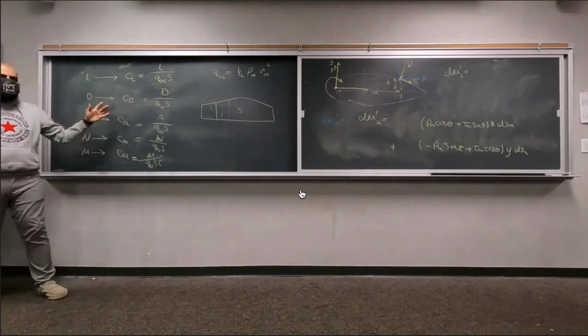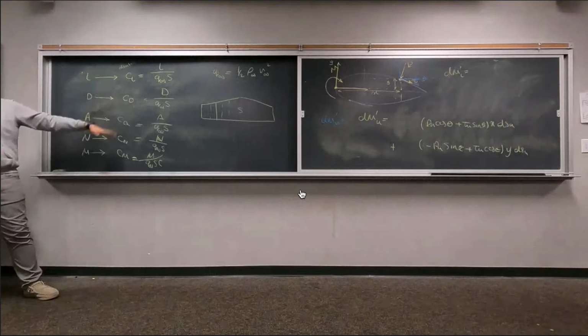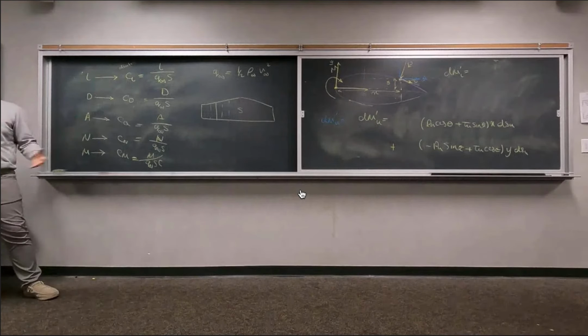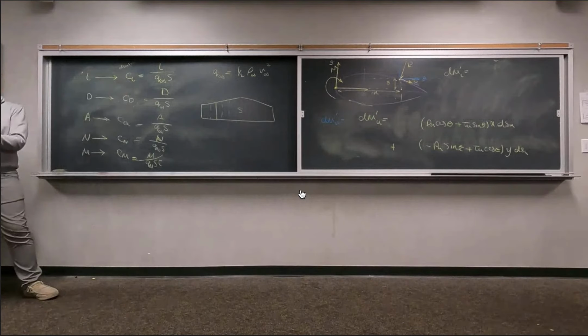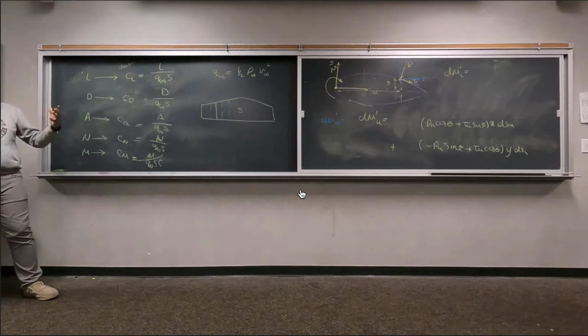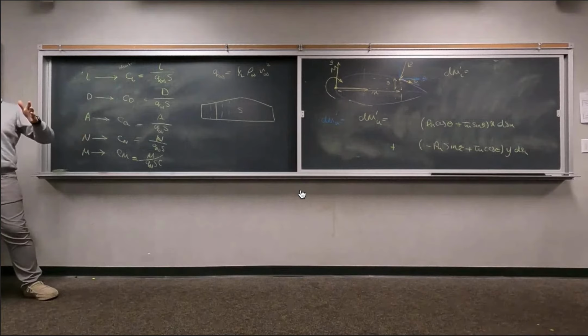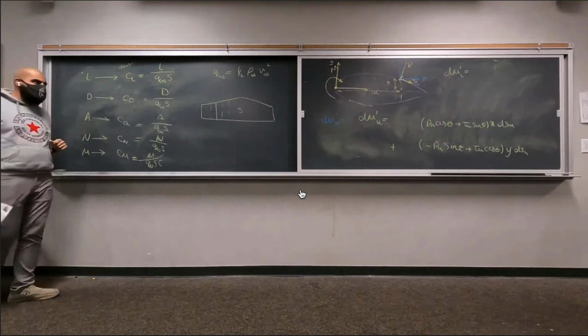And the reasoning behind this non-dimensionalization is the reason behind all non-dimensionalizations. You want to be able to scale up, right? If I calculate the lift coefficient for a small airfoil in a wind tunnel, I can apply essentially the same result to a real wing that is operating under the same condition, like a big wing. Does that make sense? So, yeah.